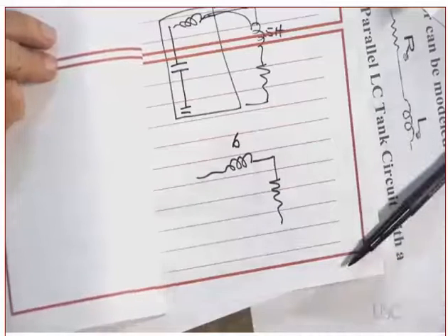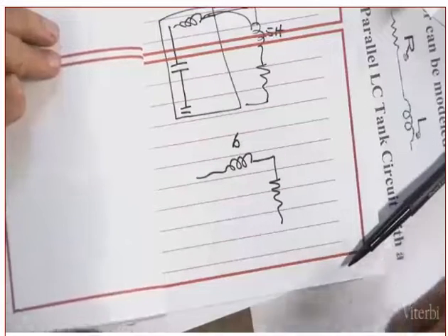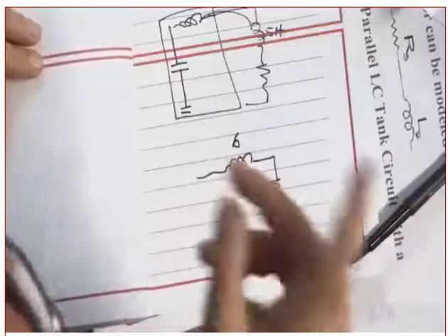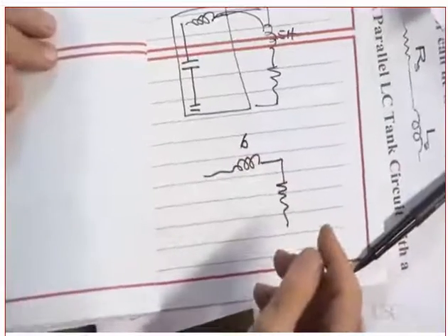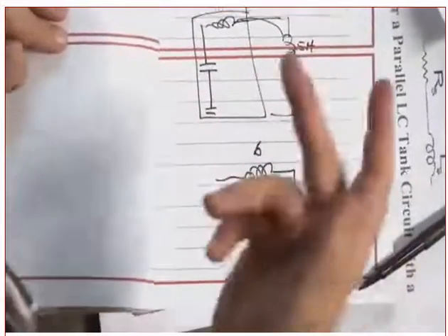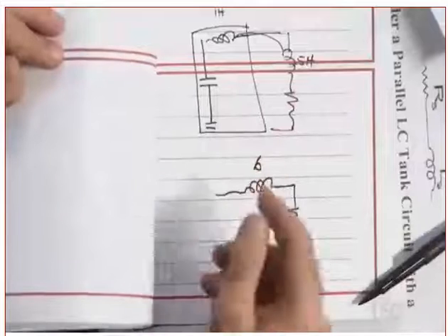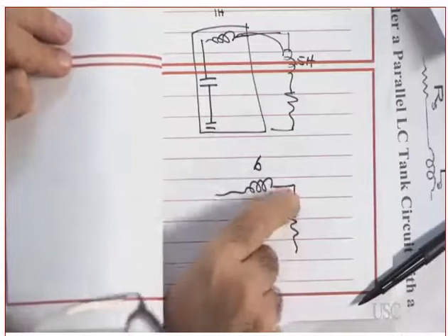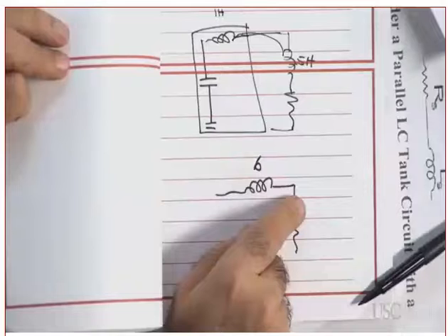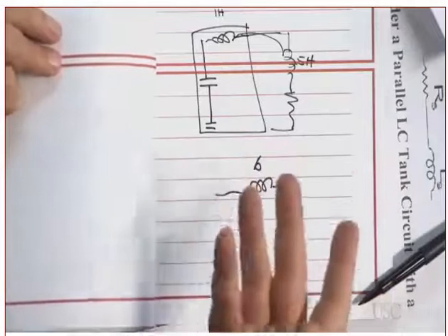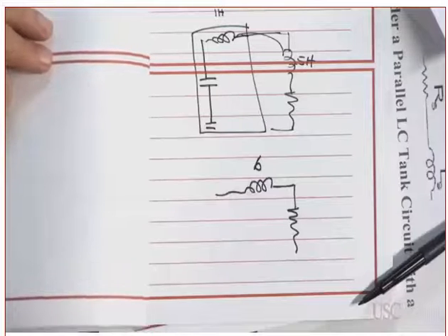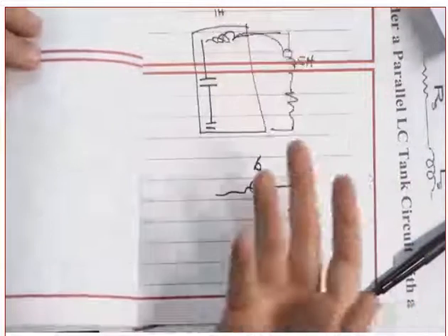It's similar to the capacitors also. But keep in mind, if the capacitors are in parallel, you sum them. But if they are in series, you need to sum them as if they were resistances in parallel. So I don't want the case in which the load is complex to bother you. Ignore the complex part. Solve the problem, match it, and then incorporate the imaginary part of the load into the matching network that you are designing.